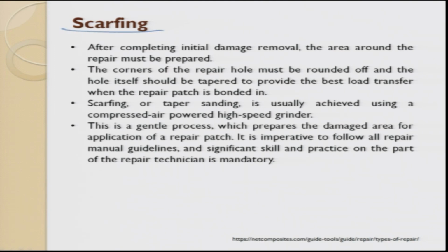So scarfing: after completing the initial damage removal, the area around the repair must be made ready. So the corner of the repair hole must be rounded off, and the hole itself should be tapered to provide the best load transfer when the repair patch is bonded to it. So basically what scarfing means is that before the damage is completely removed, you prepare the area in such a way that you get the best out of it.